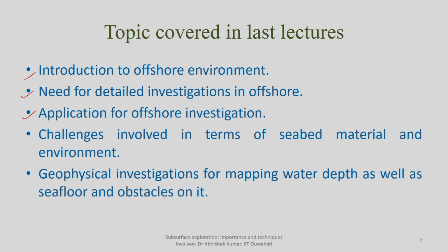Then there are possible sand dunes and the movement of sand dunes, then calcite depositions at the sea floor, which are happening at variable rates. Depending upon the binding characteristics of the calcite, it is going to govern the strength characteristics of the adjacent seabed material which has been deposited or densified. So the characteristics of that calcite, which is responsible for binding the seabed material, also govern the strength property of that material.